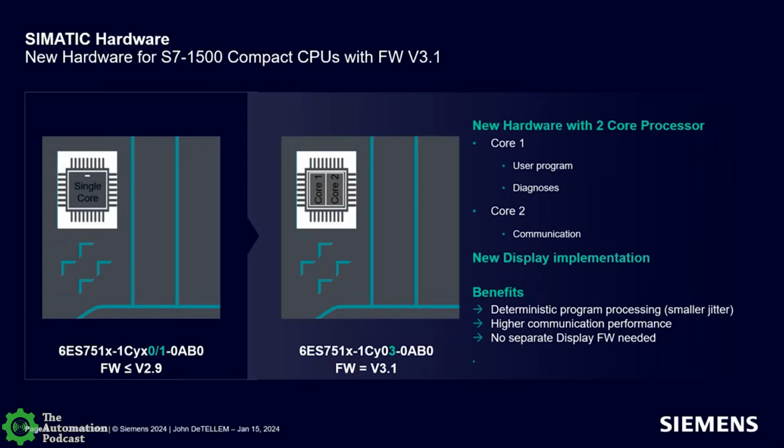Again, one of the key things that happens when we release one of these versions of the software is support for the hardware that we've been working on in the background, as far as the next release of the hardware devices. So in v18, there was a new hardware platform for most of the controllers, basically taking it from a single core PLC controller to a dual core and splitting off that communications.